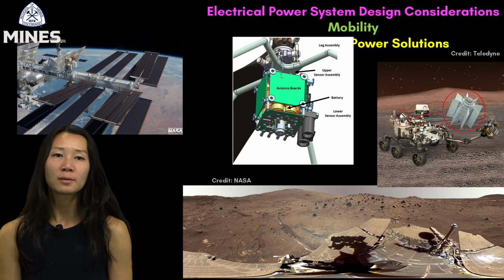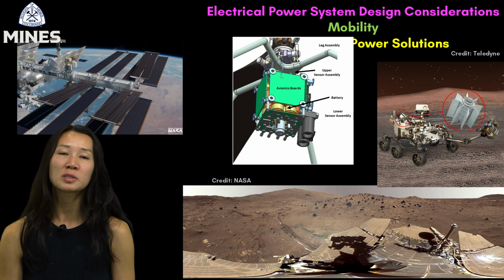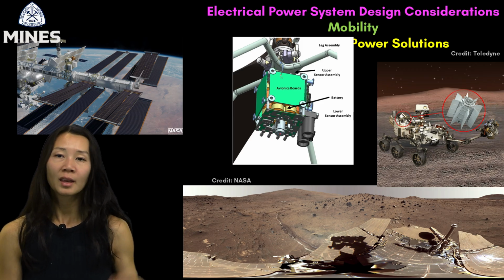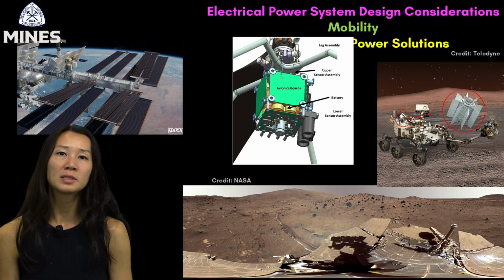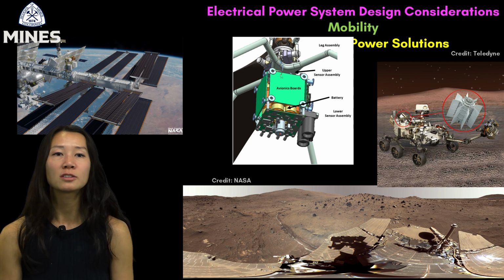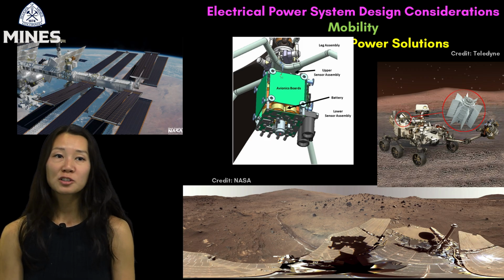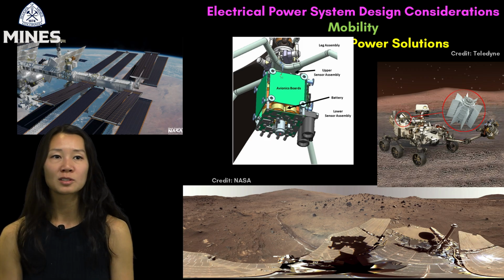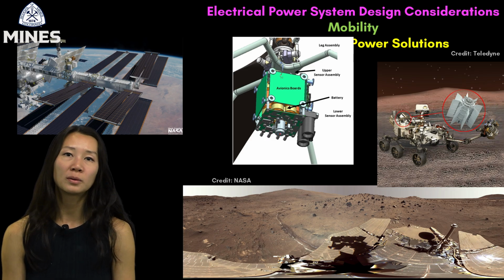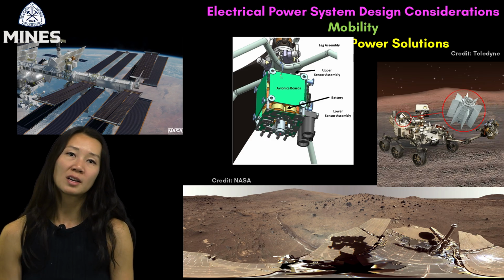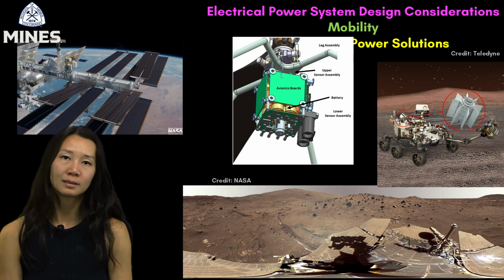This maximizes power no matter the orbital position. On planetary surfaces, mobility introduces even more variation. Ingenuity, for example, uses fixed solar panels sized just enough for a short flight per day mission, optimized for mass and recharge rate. Spirit, shown here in winter on Mars, had to park on a north-facing slope to tilt its panels toward the low winter sun, a passive way to increase solar input without mechanical articulation.